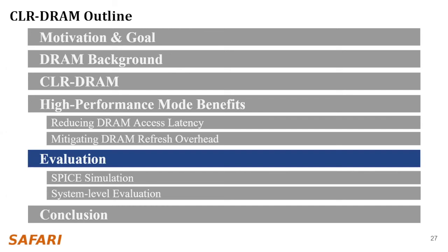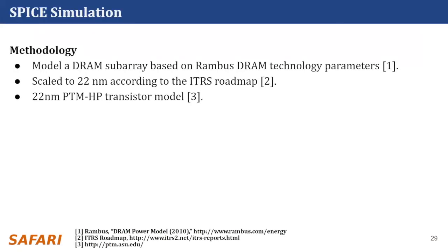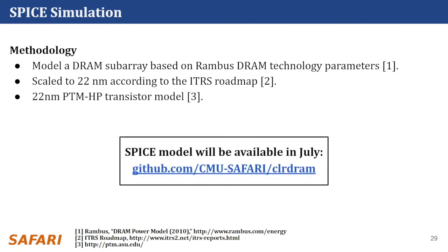Now, let me move on to the evaluation. We evaluate the latency impact of CLR-DRAM using SPICE simulation. We model a CLR-DRAM subarray based on previously published technology parameters. We scaled these parameters to match recent technology nodes. We will make our model available freely soon.